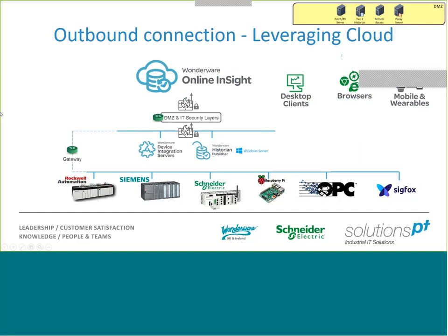Another example of leveraging a cloud solution can be seen with other variants of IoT. So not necessarily linking in SCADA and MES through the DMZ to the cloud, but linking PLCs, devices, web services, for example, through the DMZ, direct to the cloud. So not utilizing local controls. We see this through a good number of customers where data analysis is paramount, but security measures should still be adhered to and structure the connections through a DMZ.